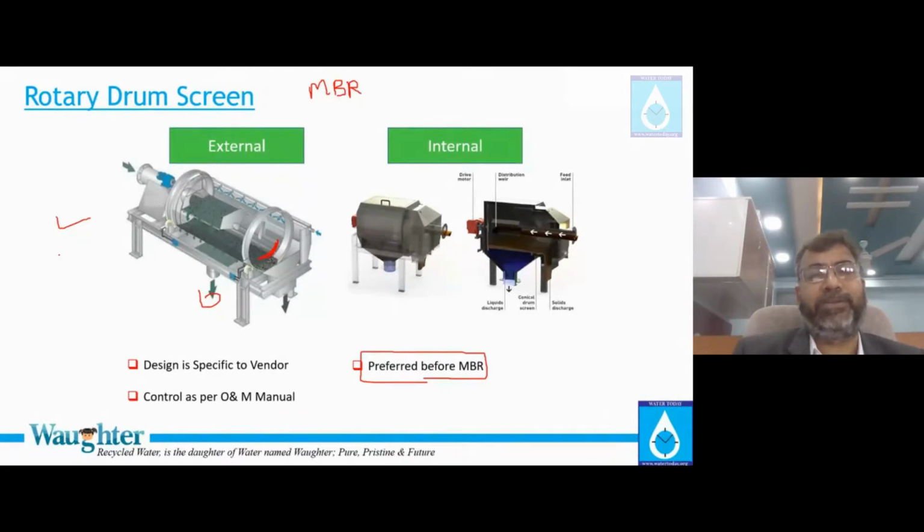Same is the case with pouches. In India, a lot of people eat gutka pouches. Those pouches are a very fine aluminum kind of material, and once rubbed, they become sharp and have the potential to cut the skin. Even things like plastic ropes and packaging material. We have a lot of very tiny plastic, and that plastic is a problem for my aeration tank. So all those things need to be removed by the rotary drum screen before you go into an area like membrane bioreactors.